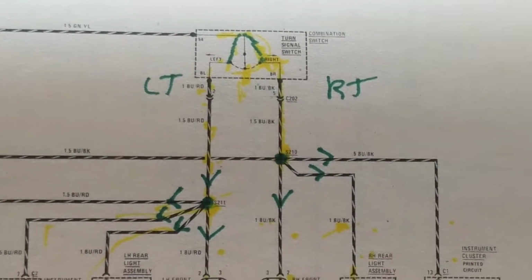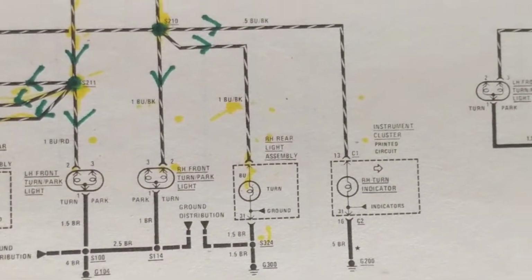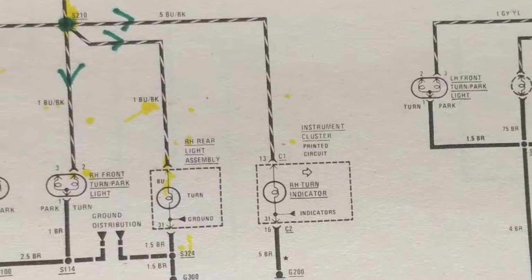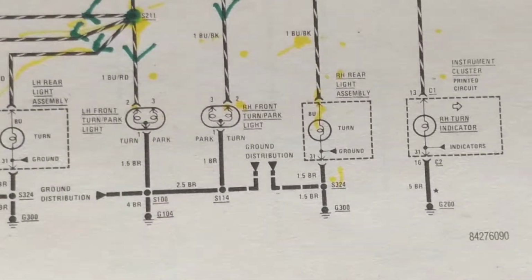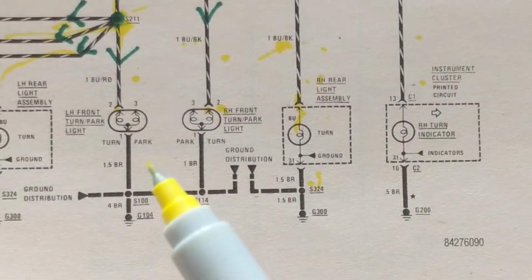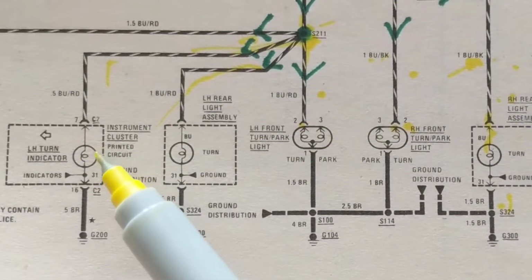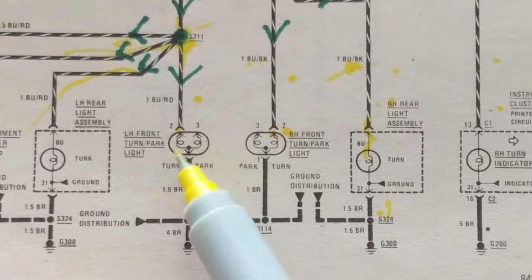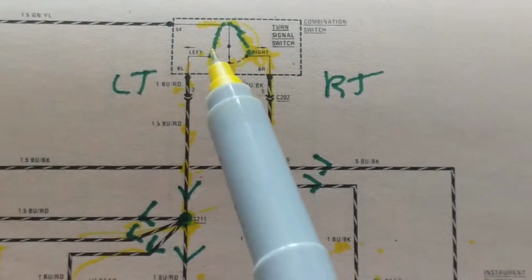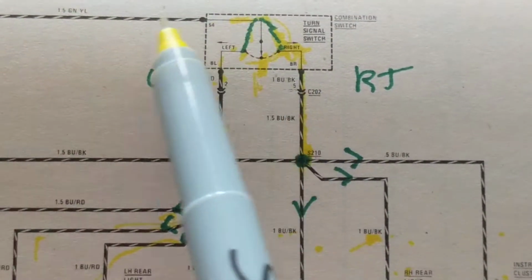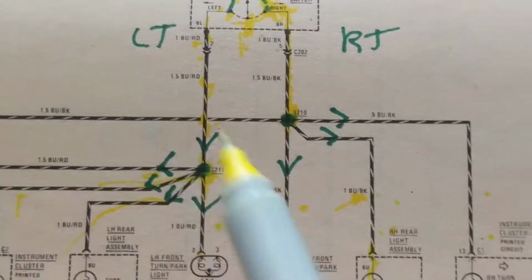If I want to troubleshoot, my left turn signal doesn't work. Well, you know what? In a quick way, I go in and look at, does the dashboard come on? Which is over here. If this doesn't work, if the rear and the front don't work, that means that the problem is maybe the switch or something over here. Maybe there is a fuse somewhere along there.